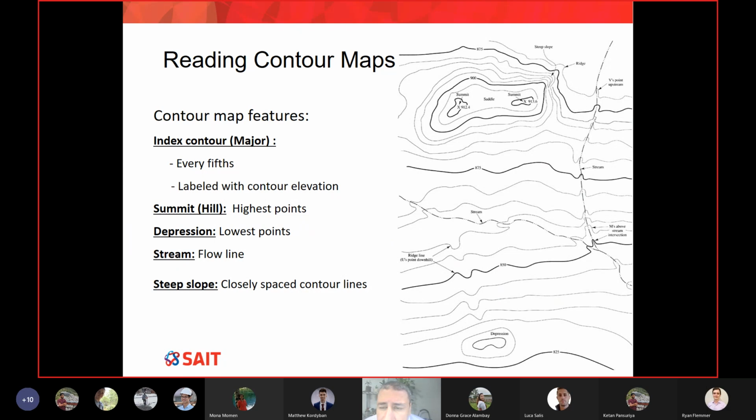Do you have labels? No. And remember, if I place a contour label on every single contour line, it makes my map so dense, with lots of text, and it is not a good idea. That's why in contours, we do not label every contour line. We only label a few of them, because otherwise it's redundant.